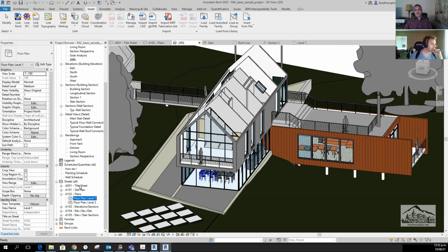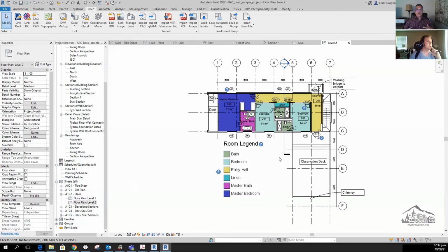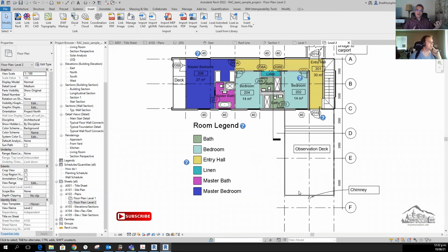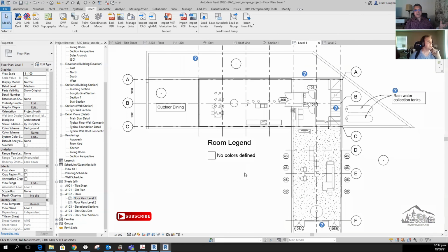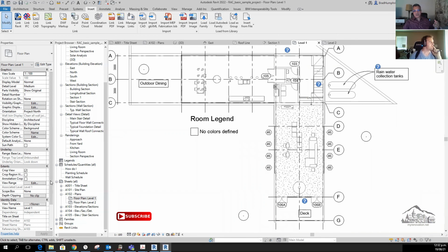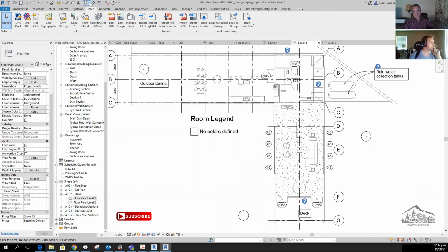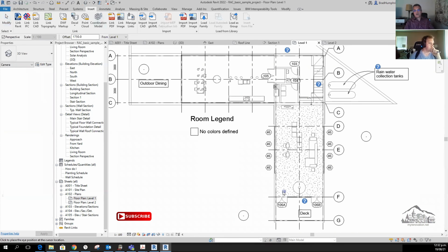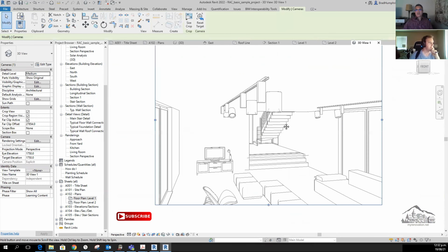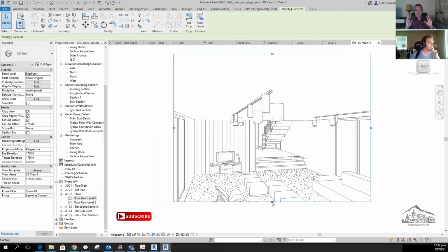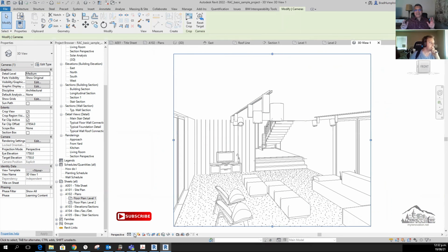So the fact that we are using Revit makes our life very, very easy, because we don't have to review. Like when I used to use AutoCAD, I used to take the drawing from the consultant in PDF format and overlay their PDF on our PDF so you can see if there is any conflict. With Revit, you don't need to do that, because you can just look at the model and you will find out exactly if there is any conflict when it comes to mechanical, electrical, structure.